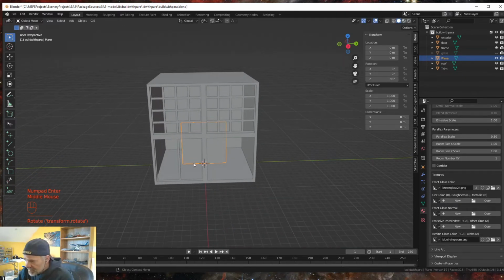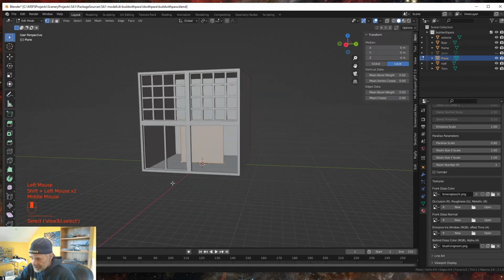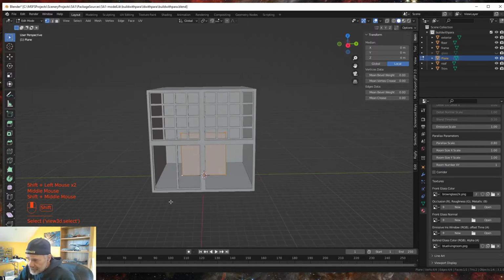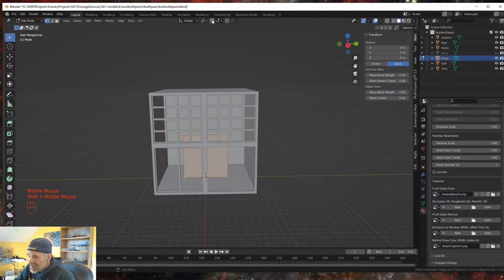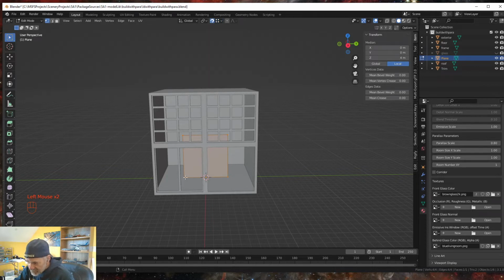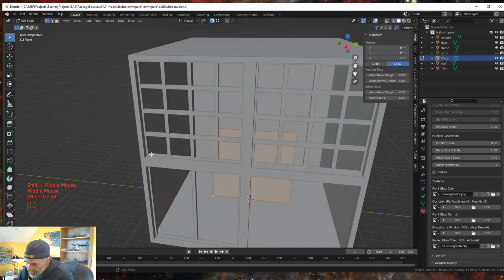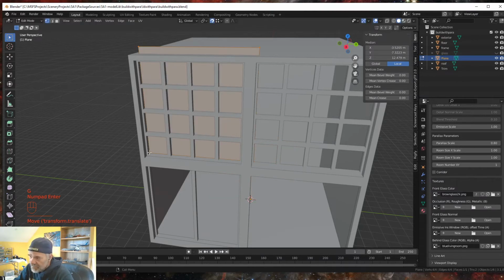Then I'm going to go into edit mode, turn on nodes or vertices, and shift click that bottom left hand corner. Make sure my snapping is turned on and it's set to vertex active. The active vertex is the white, and we're going to move that up to this corner here. Okay, so I'm going to hit G and it moves it there.